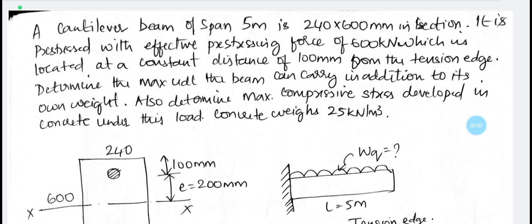However, in the case of cantilever, tension will be acting at the top and the compression will be acting at the bottom. So you have to read the statement carefully, and the expressions to compute the stress resultant also change here. Everything changes. We need to take stock of all these things carefully. Then the problem needs to be solved.